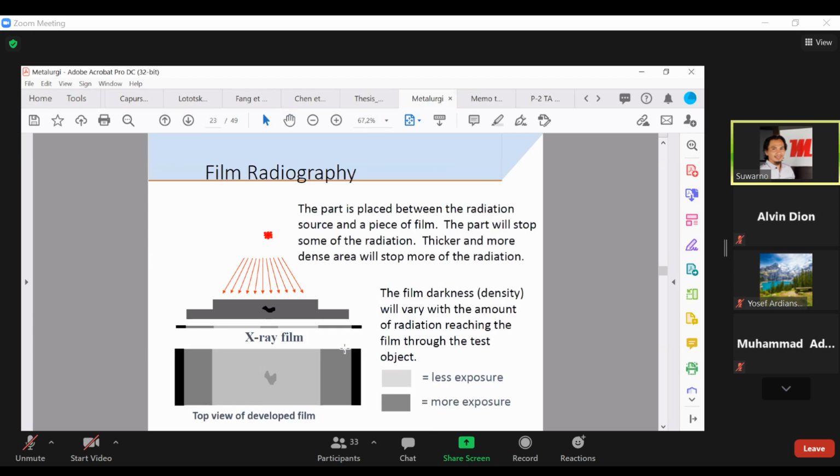So this is, for example, if you have a defect inside. So this is for defects that are inside. It's not on the surface or a little bit below the surface, which is called subsurface, but just inside. For example, if you have welded something and there is porosity inside the weld, then you can detect it with an X-ray system.